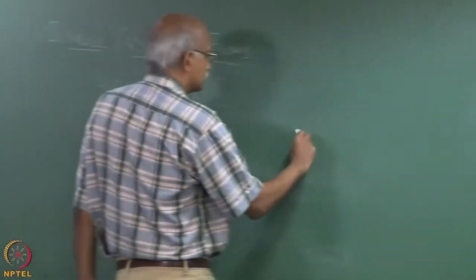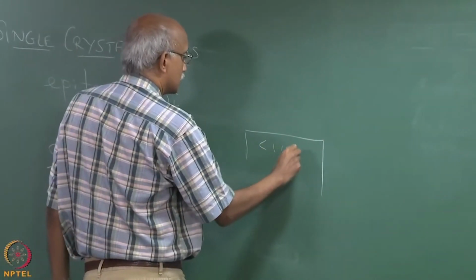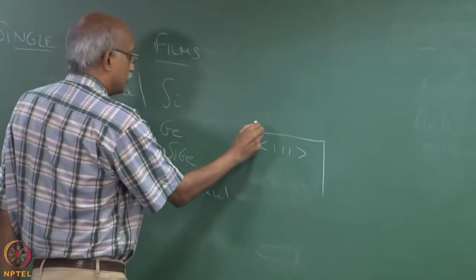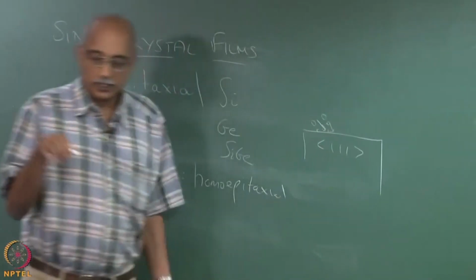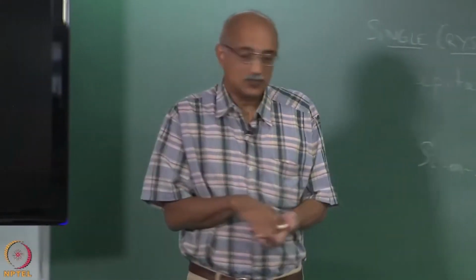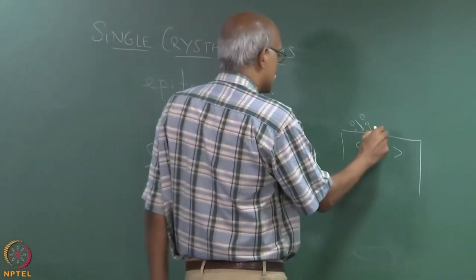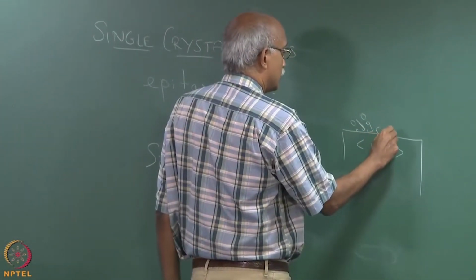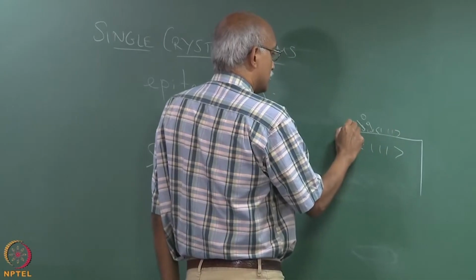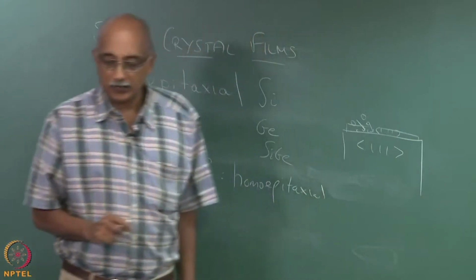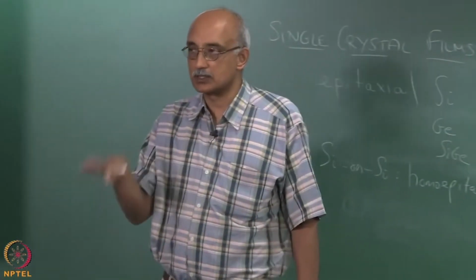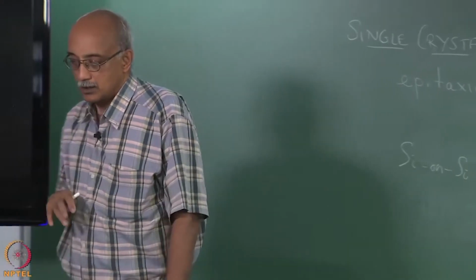So, for example, if you have bulk silicon that has a 1-1-1 structure and you deliver these vapor molecules to the surface, as they impinge on the substrate, they immediately orient themselves also in the same 1-1-1 crystalline configuration. Then you start building a structure on the substrate which exactly matches the crystalline structure of the substrate. That is how you get an epitaxial film, right.